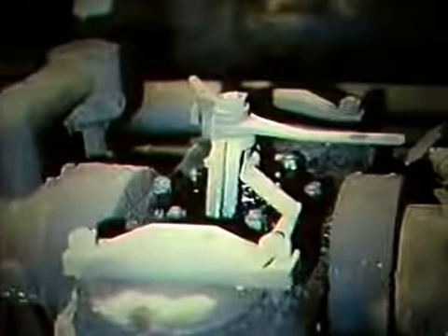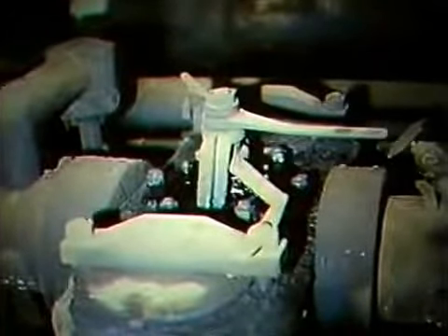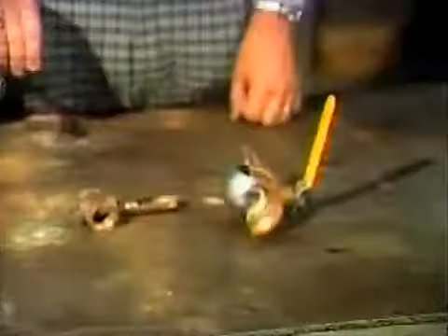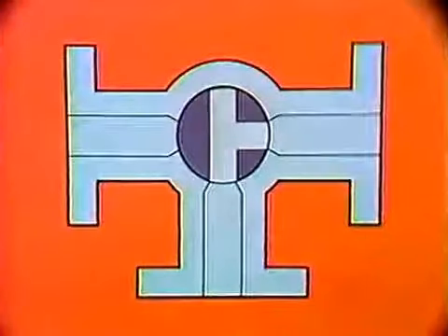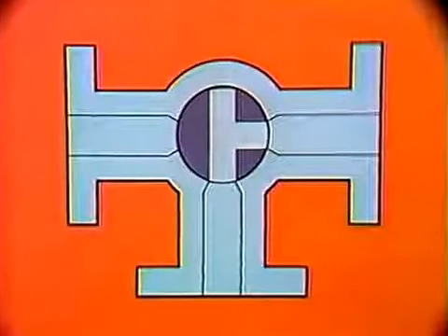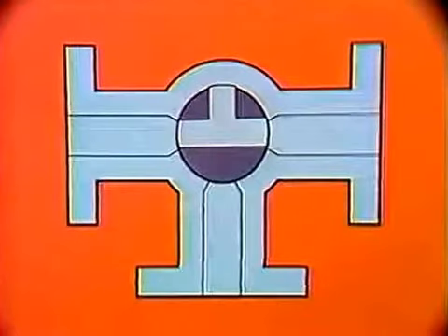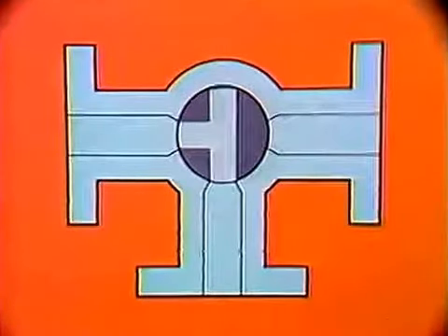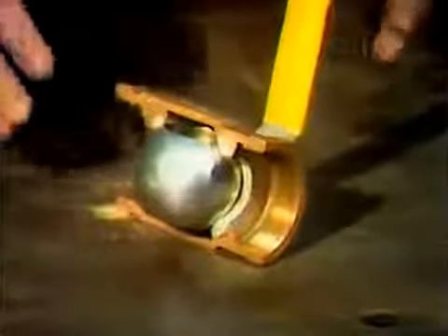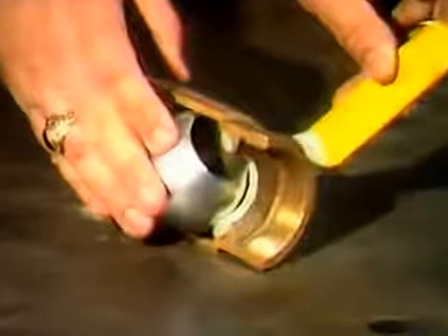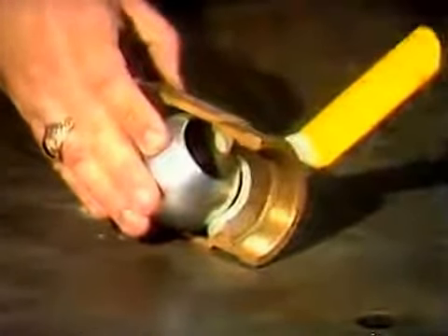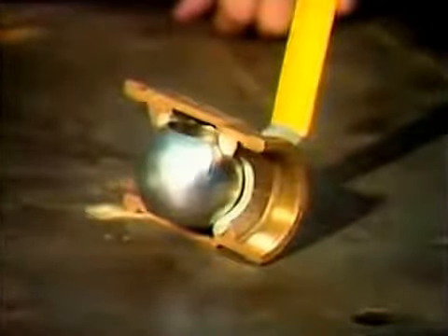Often you'll see plug and ball valves on lubricating systems, such as on a duplex strainer. A plug or ball valve can be single port, or it can be a multi-port valve. Here is a three-way, three-port plug valve. There are three different flow paths available for the flow of a fluid. But if the valve is not lined up to allow full flow, a throttling action will take place. It's not good to let that happen, though, because the fluid will put pressure on the seals around the disc as it is throttled. The seals can be damaged by this pressure, and repair work would be needed.